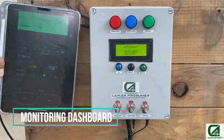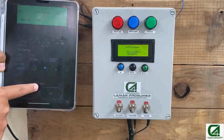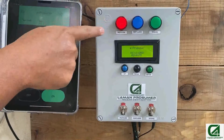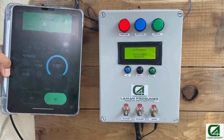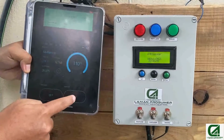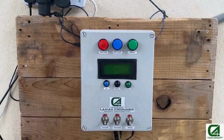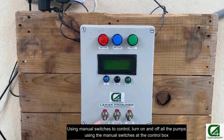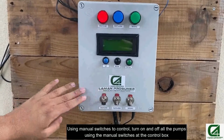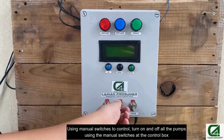Next, this system can be directly controlled from the mobile phone, which is the Blynk application. As an example, we turn on the pesticide system from the app and turn off the system when needed. We can look at the red LED indicator. In the case that the control box cannot connect to the Wi-Fi or has trouble, we can still use the manual switches to turn on and turn off all the pumps.